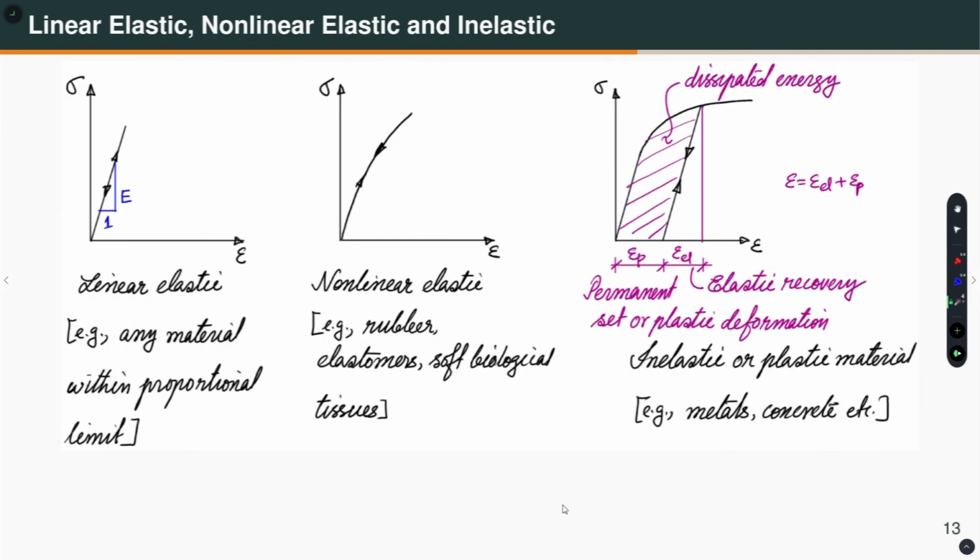On the other hand, if we look at inelastic material, for example, structural steel, the stress strain response is something like this. Let us say it is not mild steel, for mild steel you will have a well defined yield point. So, it is like this. Now, if you unload from here, it comes back following the initial slope, and if you reload, it goes like that. So, that means when you come back from here, you have some permanent deformation in the specimen.